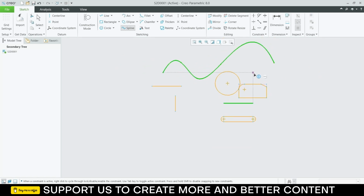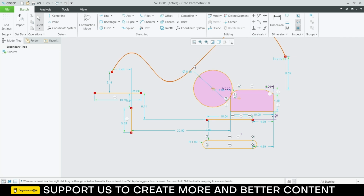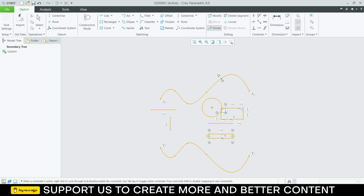Okay, now let's try to understand another command. Click on select. Suppose I want to mirror this line, so I will select this line, click on mirror. Now mirror about what line? So I will select this line. Notice it mirrors about this line. Now click on divide. As its name suggests, it divides things. So click here, notice it divides the lines. You can use it as per your requirements.